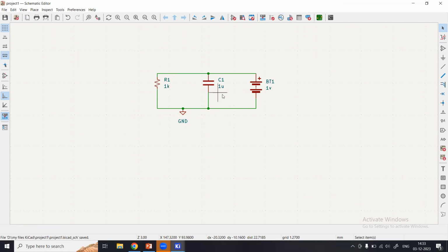So, resistor and capacitor, 1 volt. The capacitor will act as an open circuit after it is fully charged, so all the voltage will appear across the capacitor and not the resistor. And we'll just see this symbol, simulate circuit in Spice. Let's click it.